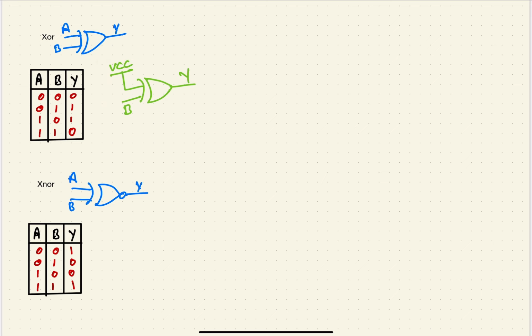And if you talk about the XNOR gate, we can see that only in one condition it acts as an inverter, that is when one input is 0, then whatever the other input is, that will be inverted as an output. So we make one input A as ground and the other input as an input.